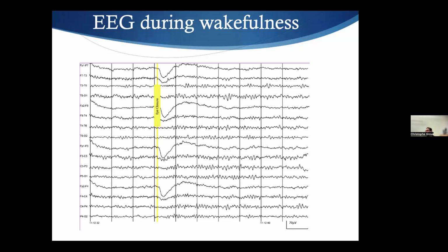If I'm doing a visual evoked potential, and I have an eye blink, the eye blink will be 10 times larger. So if your participant is blinking his eyes each time you show something, it's going to be difficult to get your response. You can always clean using post-processing, but it's also good when you make the design to allow the person to blink.